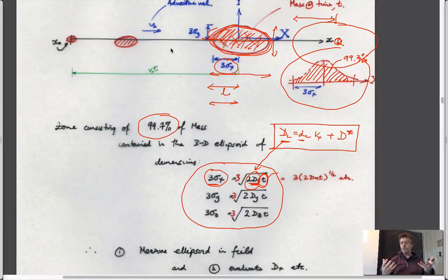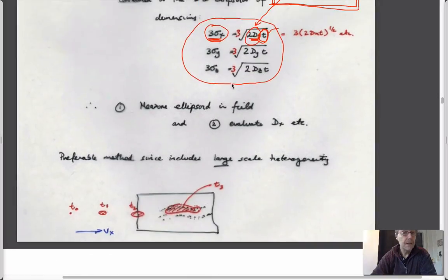Perhaps a bit more grounded in terms of physical intuition, in this case, is that you put this stuff into the aquifer, it travels downstream. In traveling downstream, it diffuses a little bit, it maybe disperses mechanically and mixes a lot as it goes in and out of the pore spaces, and spreads out as it goes downstream. So the cloud, as it goes downstream, gets larger and larger, and less concentrated. And so physically, perhaps that is not so difficult to understand, but the characteristic dimensions of it as it goes downstream will change. As a function of time, it'll get larger, and it's controlled by the mechanical properties or the dispersive properties within the aquifer, which are useful to be able to predict from one realization where it is after 10 years, where it might be after 20 years, if you don't do anything. And so that's exactly how we can use it.